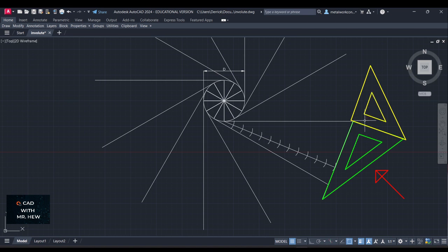Then with the 30-60 set square in place, you place another set square, the 45-degree set square, which you would likely have as a pair. You put it on the other edge, that is 90 degrees to the side that you aligned to the line.